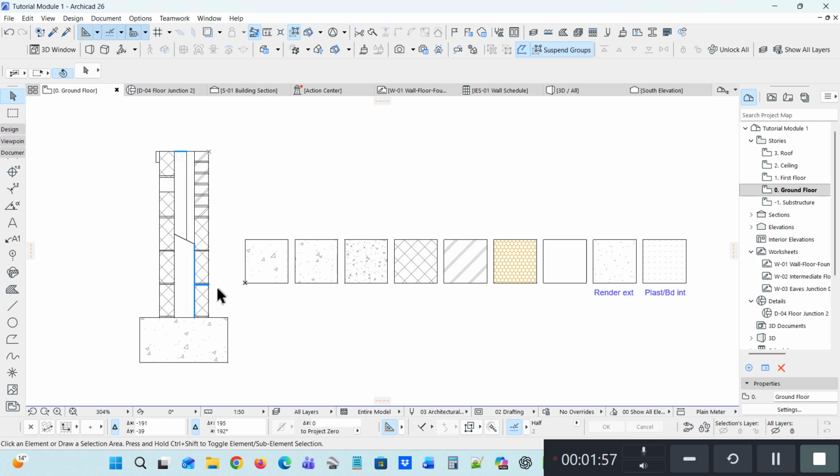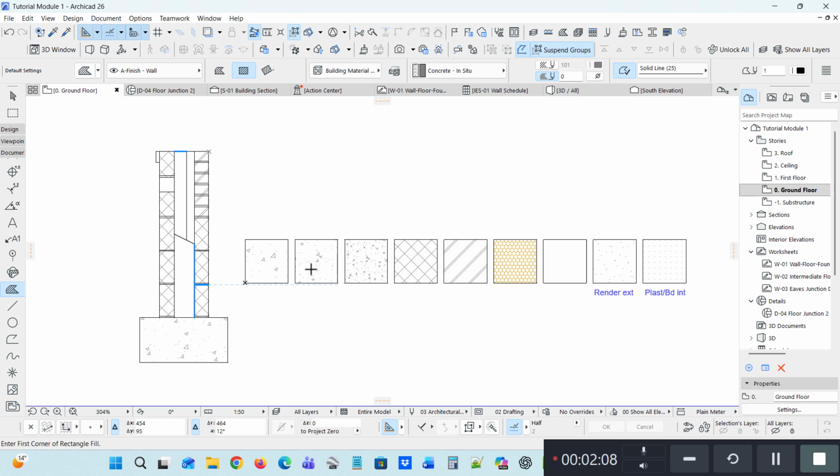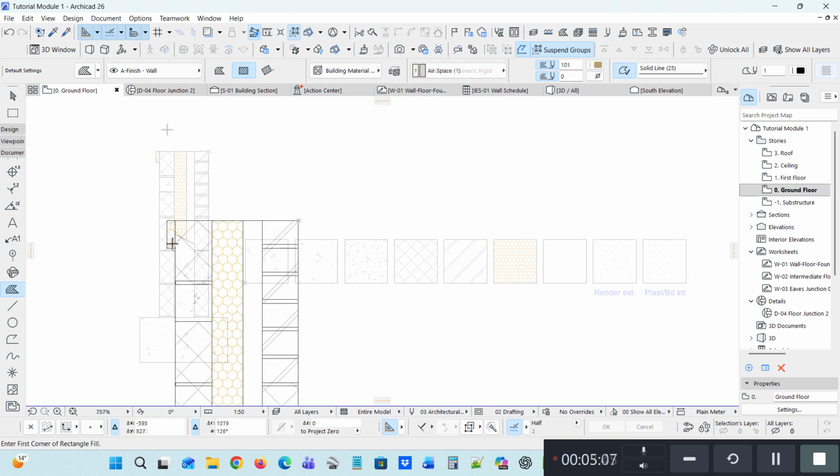So what you do now is hover above the fill you need and press Alt+C, then click in the closed polyline shape. Then press the spacebar and click. Next, I'll pick up the parameters of the dense concrete fill and place it in the rectangle using the spacebar. As you probably know, Alt+C is the shortcut for the pickup parameter tool, and using the spacebar as a magic wand will save a lot of time. I'll use this method to place the remainder of the fills.